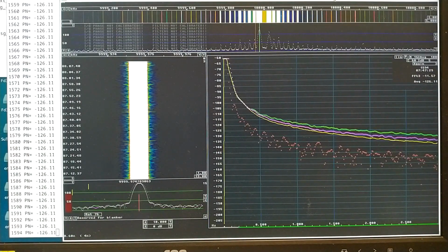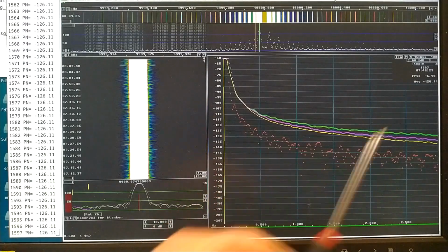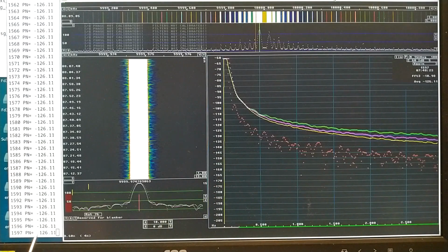The average phase noise, which is now minus 126.11, is computed for all the frequency bins that are on the frequencies where the scale here is green. It's from 0.2 up to nearly 3 Hertz. I have changed Linrad to make the first point bin number 12 in the FFT. Previously it was bin number 8. And I noted this 3 dB error. The first green point is also the first point when I show the logarithmic scale. The average value is printed on the standard error.